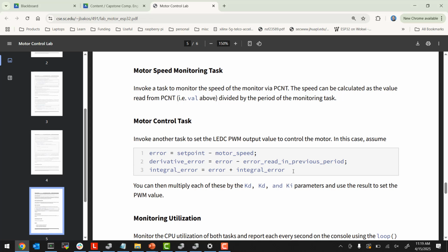These motors are, so the old motors, we deliberately bought them geared with a 50-to-1 gear ratio because we wanted to be able to control them at very slow speeds, right? Because these don't have gears on them, they're not designed to go slow. You can always assemble a few old drills and slap a gearbox on it. Yeah, if we had something like that, that'd be nice.